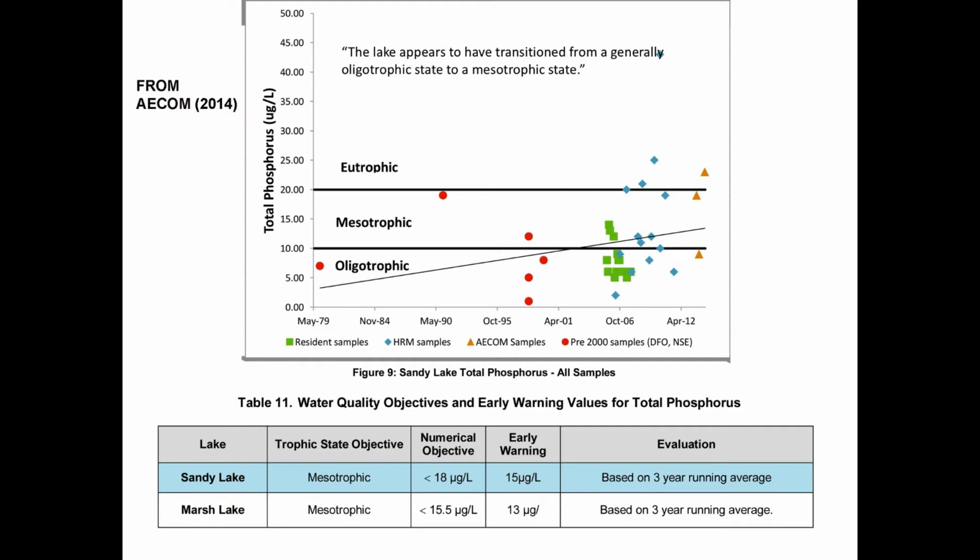So, just looking at that again, as kind of an outsider, that raised a flag with me. Now, in a sense, this is a kind of surrogate for estimating what's really happening in the lake, and a lot of what you're trying to predict is what's happening to oxygen, especially in the deep waters. The idea is that as you have higher total phosphorus, there's more productivity, there's more material to sink down and consume oxygen in the deeper waters, and then make it go too low for the salmonids. They need relatively high oxygen concentrations.